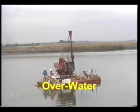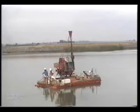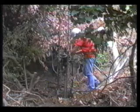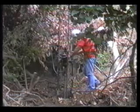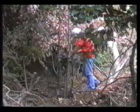For soil investigations beneath bodies of water, an overwater drill rig must be used. Some overwater rigs consist of a customized barge where the drill rig is positioned in the center and drilling takes place through a hole in the deck. Portable rigs can be partially machine operated, as shown here, or operated manually. These rigs typically have a depth limit of about 25 feet, depending on the subsurface conditions, and are used when access by an off-road rig is impossible and the expense of a helicopter is not justified.